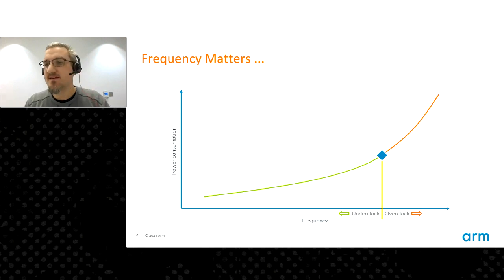So if you're a PC hobbyist, and when I was a teenager, I loved overclocking my PC, you're used to it going up and having to put a bigger heatsink and whatnot to cope with the overclock. The good news for mobile is it also works in the other direction. If you can underclock and reduce voltage, you get that V squared saving working in your favor. So optimization for mobile is often about trying to simplify the workload to the point that a system can start dropping clock rate, and you get that power curve working in your advantage rather than the other way around.